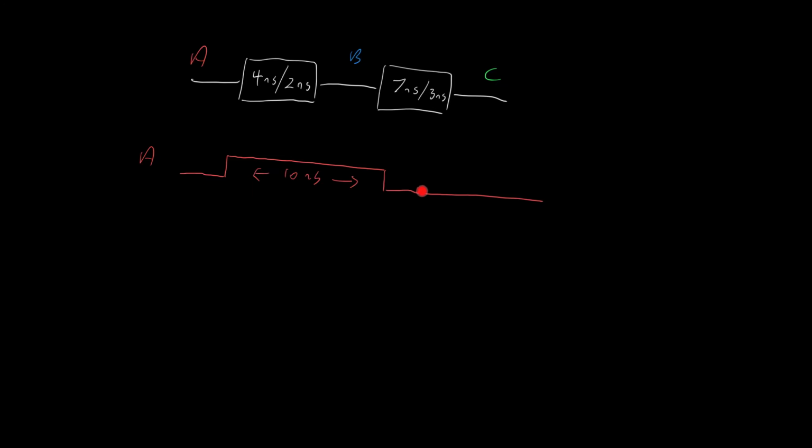Here we have the input waveform going in here at point A. We assume that prior to A, the logic circuits are in equilibrium. We've got steady outputs, and for simplicity, let's assume that the transfer function is just that the output's going to be equal to the input. Normally we'd have multiple inputs and some more complicated calculation going on. Remember, logic circuits implement truth tables, but we're not going to worry about this here. We're just going to focus on the effect of the contamination and propagation delays.